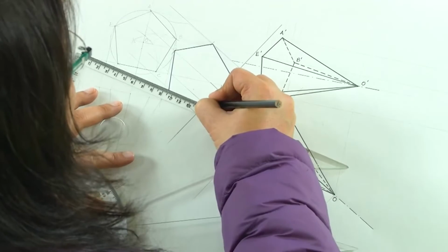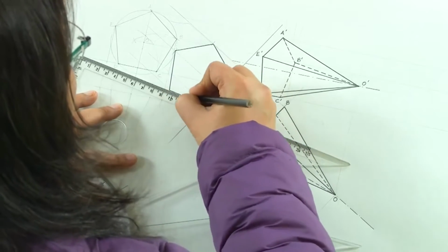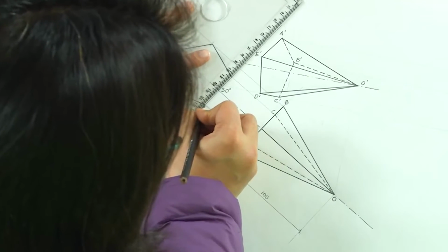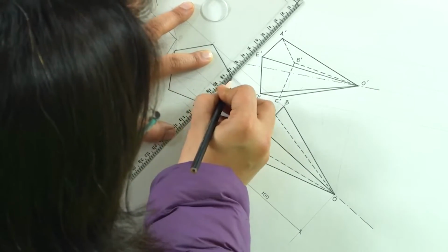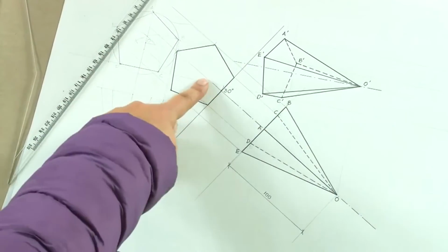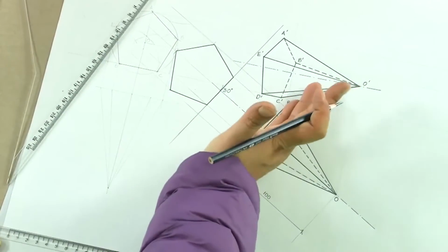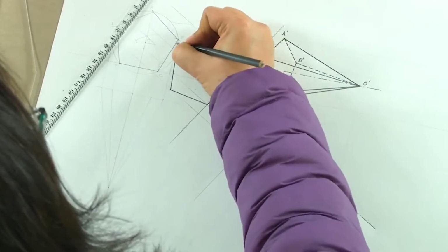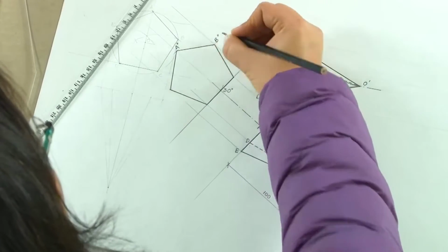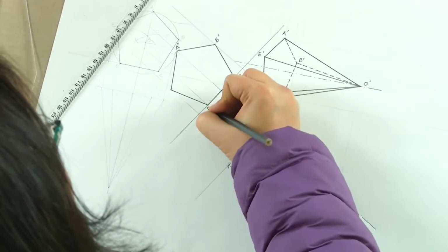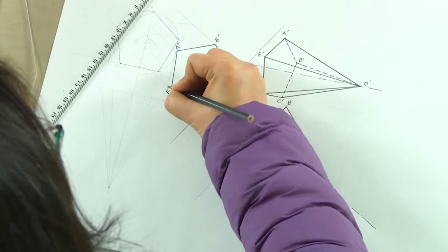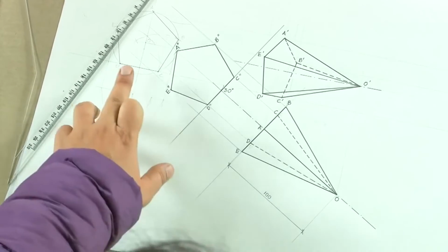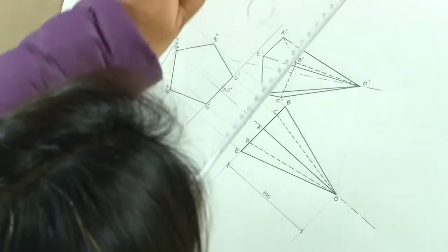So, what we have here is, if you check the shape, this is the true pentagon, because what we have drawn is the base on a plane which is parallel to the base, and hence we will get the true pentagon here. So, what we have here is A, B, C, D and E. So, we have the true pentagon here on the auxiliary plane,